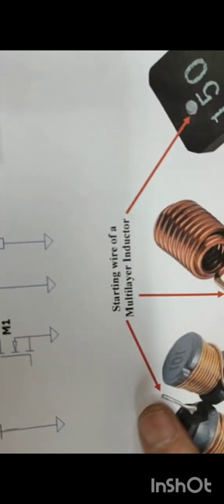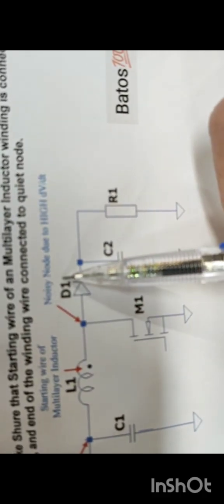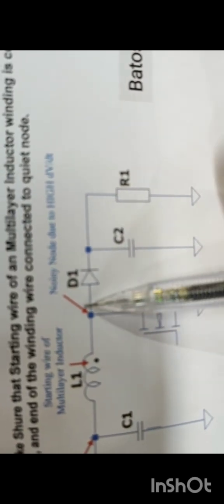According to Maxwell's equation, it basically states the rapid change, and that is dV/dt, voltage over time. At that particular point of rapid change is where the highest EMI noise, electromagnetic field, will be generated, and which is usually the point of the inductor connected to the switching, or should I say noisy node, because this is where all that switching is actually done.